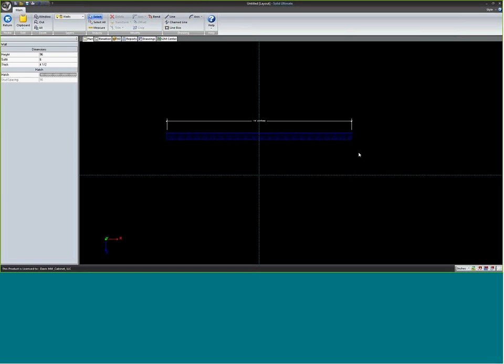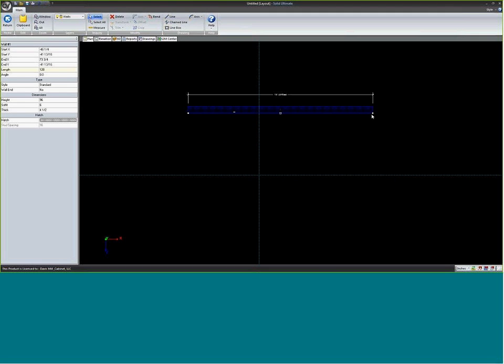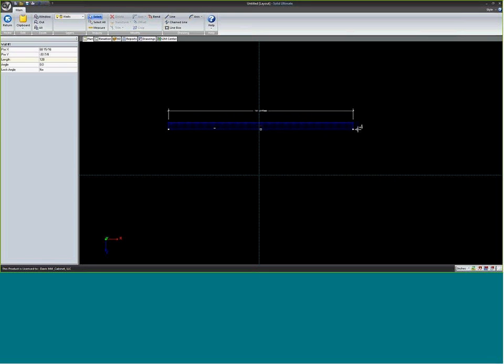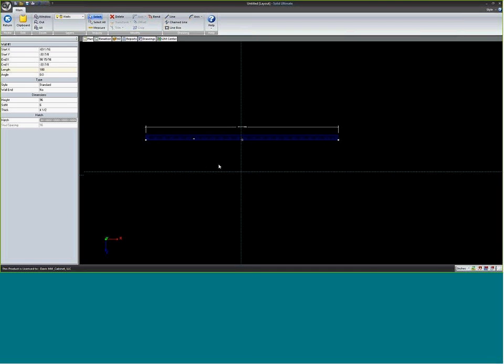You can move walls by themselves just fine by clicking on that wall, clicking in the center and moving it around freehand, or you can use this to move it parallel to the existing wall. Handles on the ends of walls can be used for resizing walls. So if I grab that, I can either drag it out to whatever size I want, or I can, again, type in the dimension, and it will jump to that size. It expands the direction I'm pulling that. So whichever way I'm going, and I type in the new wall length, it knows to follow my cursor.